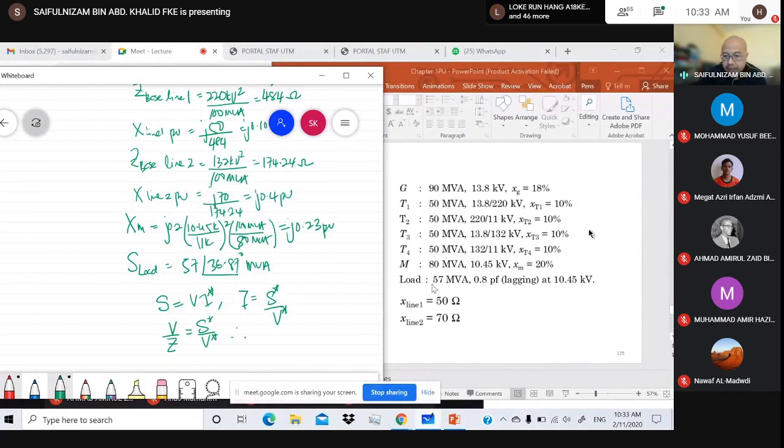we want to find the impedance, right? Load impedance, the actual load impedance. Then we can find the per unit. After finding the actual, we can find the per unit value, right? So the load Z equal to V times V conjugate over S conjugate, right? So this is equal to V square over S conjugate.